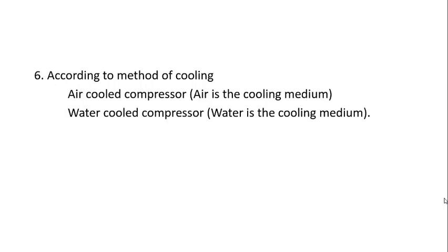Another classification is according to the method of cooling. If you increase the pressure of a flowing fluid, the temperature of the fluid also increases, so we have to cool the fluid. If we use air as a cooling medium, it is an air cooled compressor; water as a cooling medium, then it is a water cooled compressor.